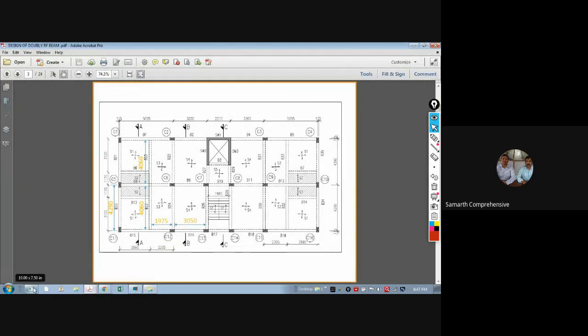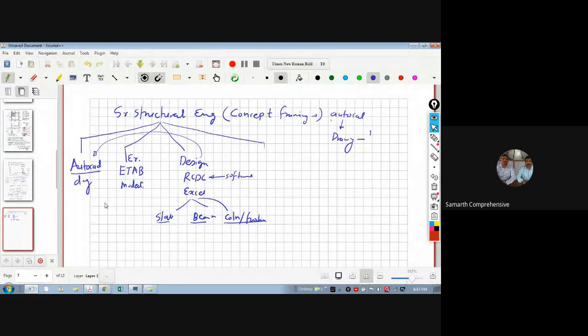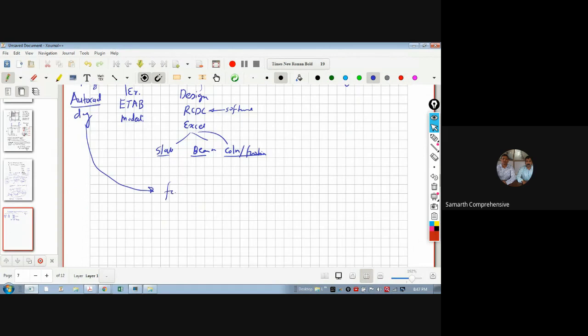So there are a lot of drawings. Okay. So in AutoCAD drawings, if it is a building, then we have a foundation drawing or footing drawing, let's say. So the footing drawing has the schedule of footing, that is reinforcement sizes and so on. There may be details, like I told you, cross section of footing, development length, lap length and so on. So the footing drawing carries this, and then footing layout, plan of footing. You will see that in training, but okay.